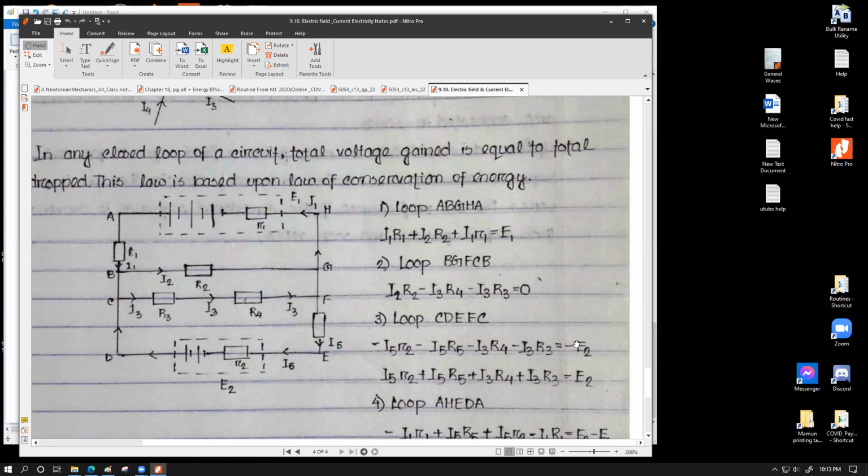So the EMF plus or minus sign is not dependent upon the current direction. Current direction dictates what is happening on the left side of the equation. The plus or minus of the source comes from a single judgment: would the battery exclusively on its own produce the current in our considered direction or the opposite? If it is the same, positive EMF. If it is opposite, negative EMF.